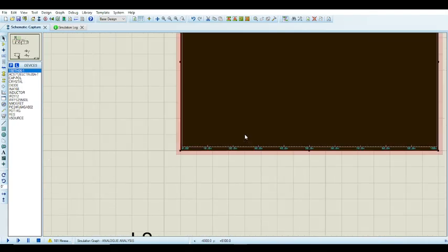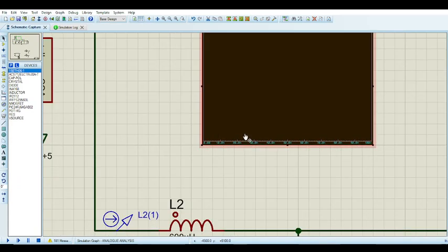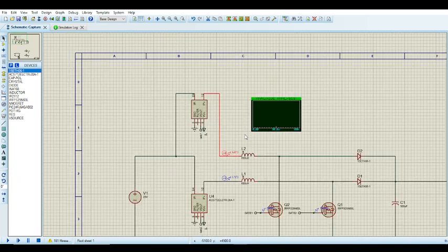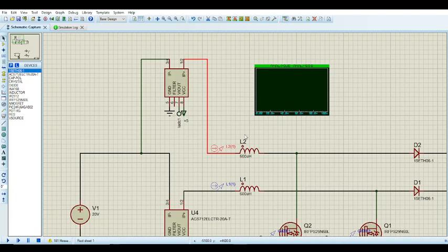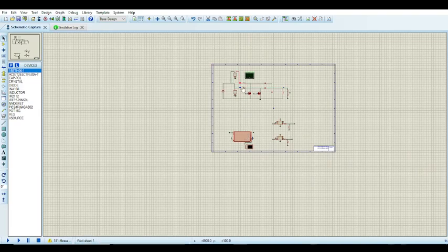I use this particular software because remember, it's a microcontroller and a spice analysis together. And spice analyses are fairly, I don't want to say super accurate, but they're a fair representation. And as for the microcontroller, it's very close. When you simulate what a microcontroller is doing in simulation and in the real world, they're very close. Because remember, we're dealing with ones and zeros here, as opposed to an inductor, capacitor, diode, which are largely analog devices, and these sensors as well. But when we're talking about the microcontroller, it's digital. It's essentially the model of what's in the actual chip is the same as what's in here. It's the exact same model.